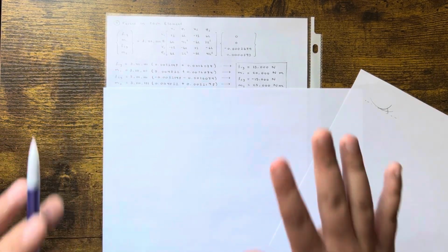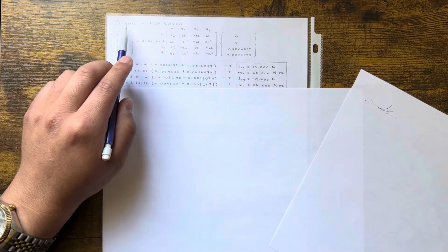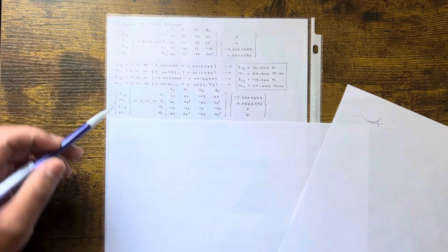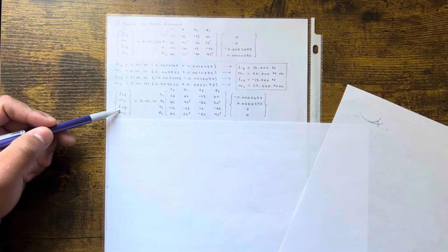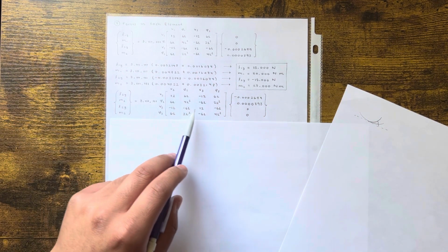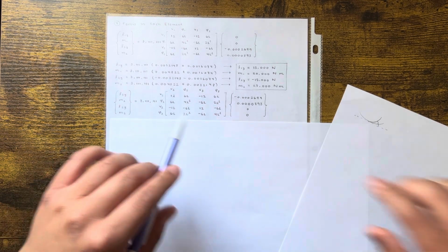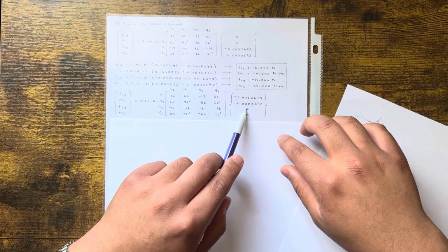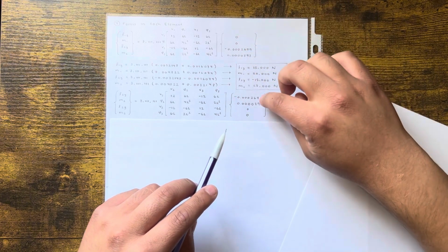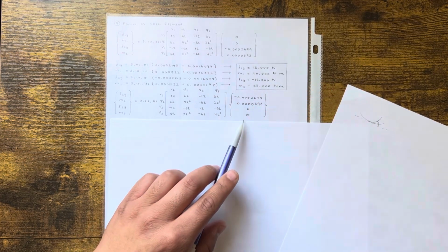Now, we'll verify these numbers, but first you have to calculate every single element's forces in each element, okay? So we did the first one, now let's do the second one, right? Second element is between nodes 2 and 3. So same thing, right? You use a 12, 4L squared, 6L, 6L, okay? You don't use 24, 0, 0, 8L squared. Once you do that, now V2, Phi2, V3, Phi3. Notice how these just shifted up, right? Because this one that went from nodes 1 to 2, now you're going from 2 to 3. So these two went up, and then V3 and Phi3 are right here.